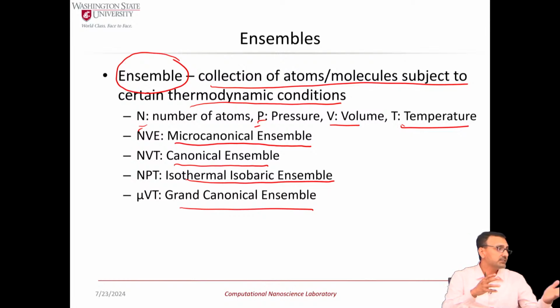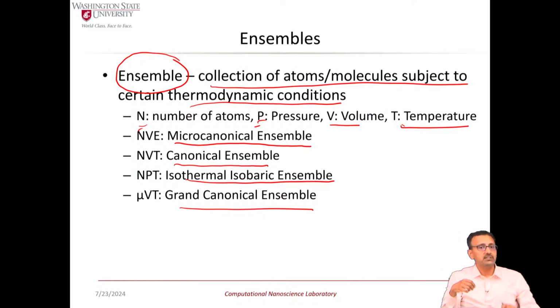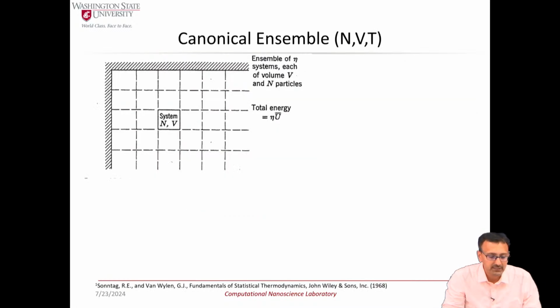So, maybe a separations process, catalysis, then the grand canonical ensemble is pretty handy to work with those systems, because what you want to hold constant there is a fixed, let us say, partial pressure of a gas around a solid surface. So, if the number of particles is fixed and they start depositing on the surface, the partial pressure will change. So, you have to replace them by adding additional particles into that system, which is achieved through a grand canonical ensemble. Just this is kind of an aside.